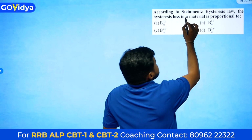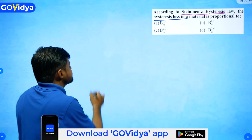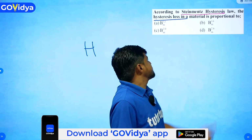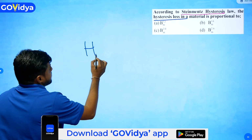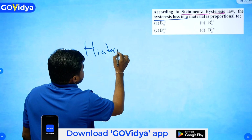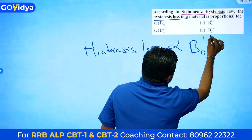According to the Steinmetz hysteresis law, the hysteresis loss of a material is directly proportional to Bm power 1.2, Bm power 1.6, Bm power 2 or Bm power 2.6. Hysteresis loss is directly proportional to Bm power 1.6.